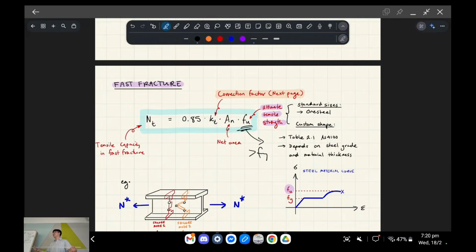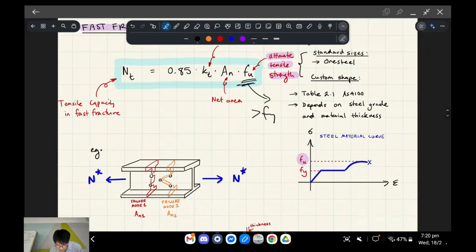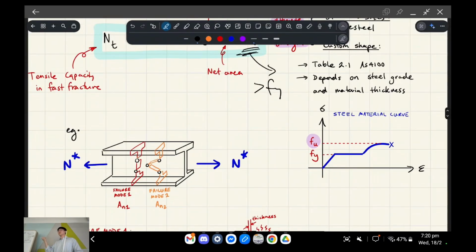Perfect, yeah, because you did maths. That's right. You might remember fast fracture is propagated from cracks in that course. So cracking can lead to this kind of brittle failure mechanism in tension. What happens is when you have bolt holes, which is very common, because to connect two bits of steel together you can either bolt it or weld it, bolt holes are very common.